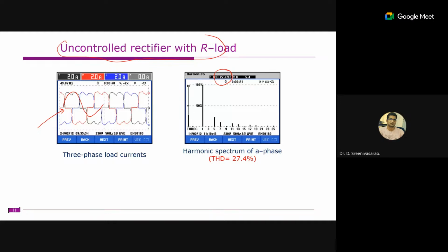That means the load itself produces some harmonics, and the converter itself eliminates those harmonics as well. So if you are using 100% power converters that rely on active rectifiers, then in this case the DSTATCOM or power quality solution, the power quality problems will not arise.